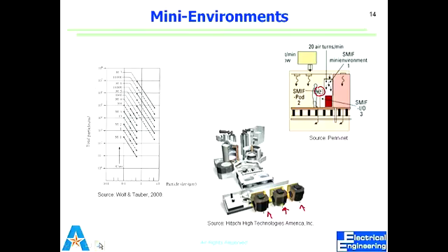So what would class 1,000 mean? Look at the plot. It starts from here and goes down. So bigger particles are way smaller in their quantity. Make sense? These plots make sense? So bigger particles are much less in number, right? And then we go all the way to what size? 0.1 micron. How much is 0.1 micron? 100 nanometers, right? How many do we allow? 10 raised to power... wow, a little close to a million, right? As the size goes small, it becomes hard to filter that.